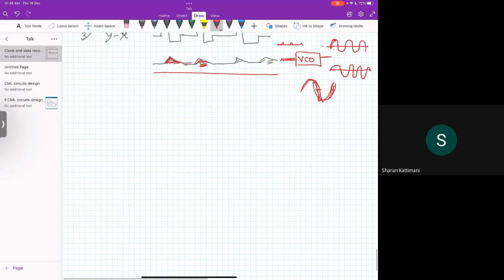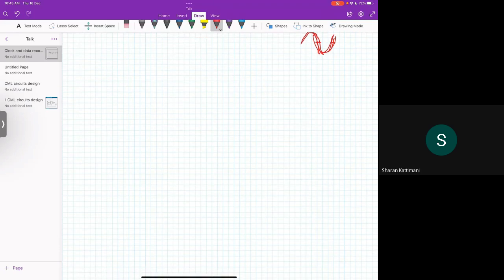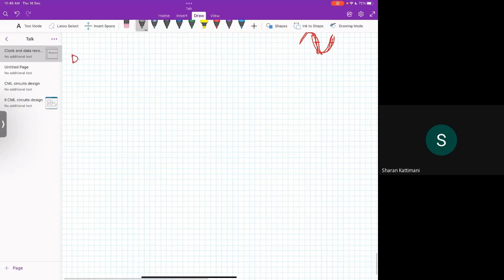So people have thought about how we can get rid of this kind of problem, and they came up with the binary PD. They say, why do we need to work with the full signal, why can't we take a decision based on 0 and 1? We need to find whether data and clock are aligned or not. So we can decide that if data is ahead, then it is 1, and if it is not ahead, then it is 0. Can't we decide in this manner?